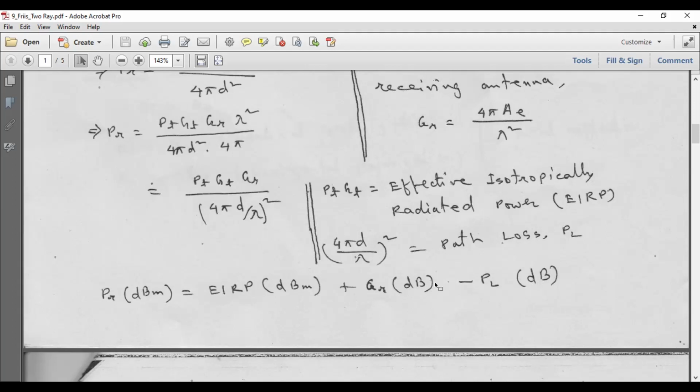When you are separating, you still have the log term, right? Yes, sir, the log term is there. As long as you have the log term, you should use the unit dB. PL also has the base 10 log multiplied by 10. That we are not removing. We are just converting one unit, like taking 1 meter as millimeters. Our reference is 1 milliwatt; we are just showing it with this one, but actually we have this 1 milliwatt reference with the whole thing.